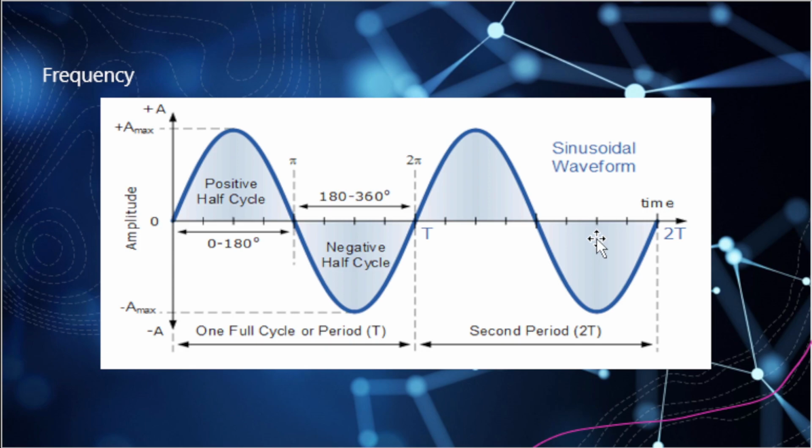Direct reading frequency measurements can be made by instruments using series frequency selective electrical networks, bridge test sets having null indicators, or counting type frequency meters as mentioned. Frequency measurements for radio equipment are made during tuning, preventative maintenance, and corrective maintenance procedures. The type of test equipment selected always depends on the frequency that's being measured, the required accuracy, and the amplitude associated with that frequency.